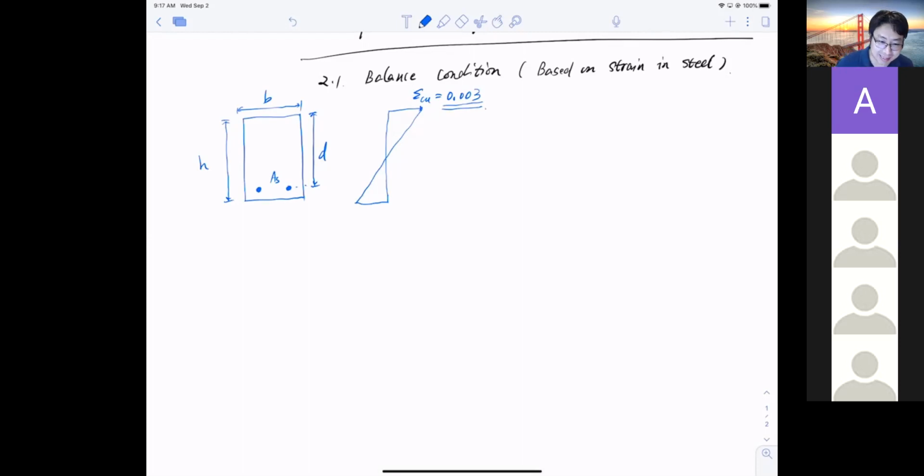One more digit. Okay. A good answer. Remember that. That's the failure strain for concrete. It does not change. So we say this is the neutral axis right here. And I have my steel right here, and we reach a strain in the steel, epsilon S. So this is my compressive zone C.